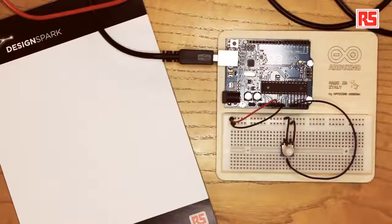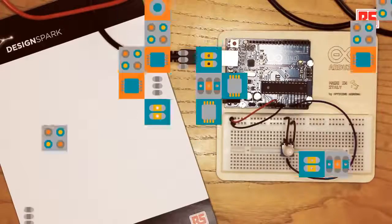And then there is a little menu at the bottom that normally says 9600, and that's, for example, the speed of communication used by the Arduino to send the data. So the speed of sending by the Arduino and the speed of receiving by the Arduino IDE have to be the same in order to keep the data readable.